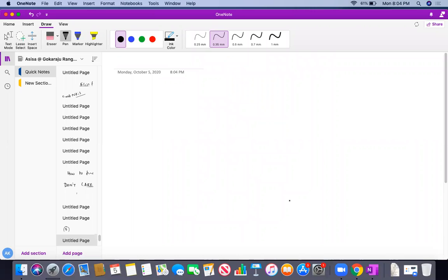Till now we have discussed that there are certain fundamental assumptions for flip-flops. Am I correct, students? But I have not yet told, and somebody may counter attack me: why, sir, are you always taking Q equal to 0, Q bar equal to 1? Why not Q equal to 1, Q bar equal to 0? Yes, obviously you can take that, but the question is how to take it. If I just tell it like Q equal to 0, Q bar equal to 1, will it happen? No. So we have to set the outputs, or give some initial conditions to the flip-flops.